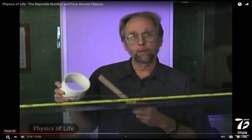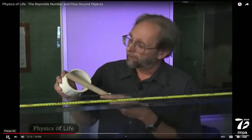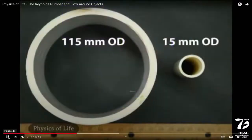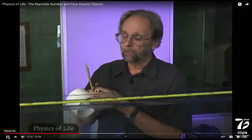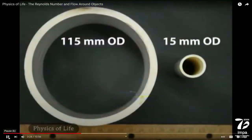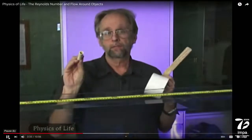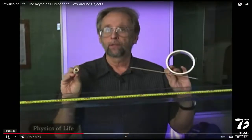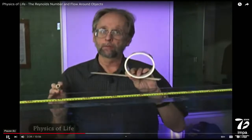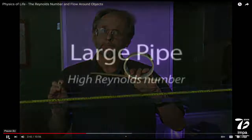An important part of the Reynolds number is the diameter, and in this case, the diameter of this PVC pipe is 115 millimeters. So there are two different pipes, two different sizes, which changes the Reynolds number, of course. The speed is fixed, and the liquid is fixed, so you can change the Reynolds number by changing the radius. This small pipe will give a Reynolds number about 1/10 of the Reynolds number that we get with the large one.